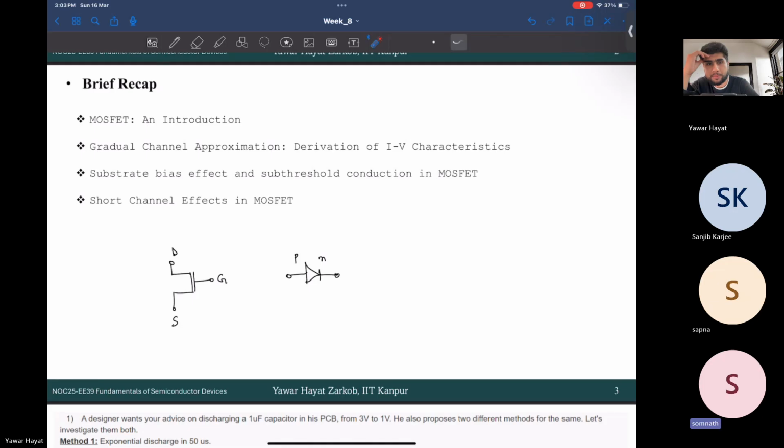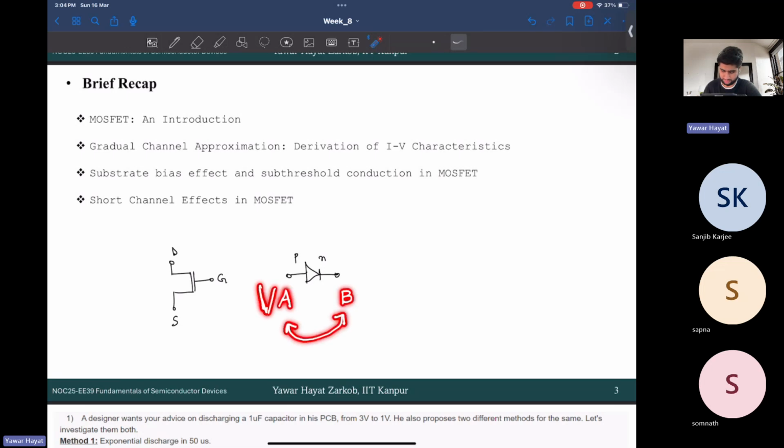I think it is asymmetrical because the work function levels are different, sir. Yeah, the thing is, when you interchange the polarity, right? Suppose I am applying a bias A to the P node, and I'm applying some bias B to the N node, right? When you interchange these two biases, if the characteristics remain the same, then that is a symmetrical device, right? I mean, in layman's definition.